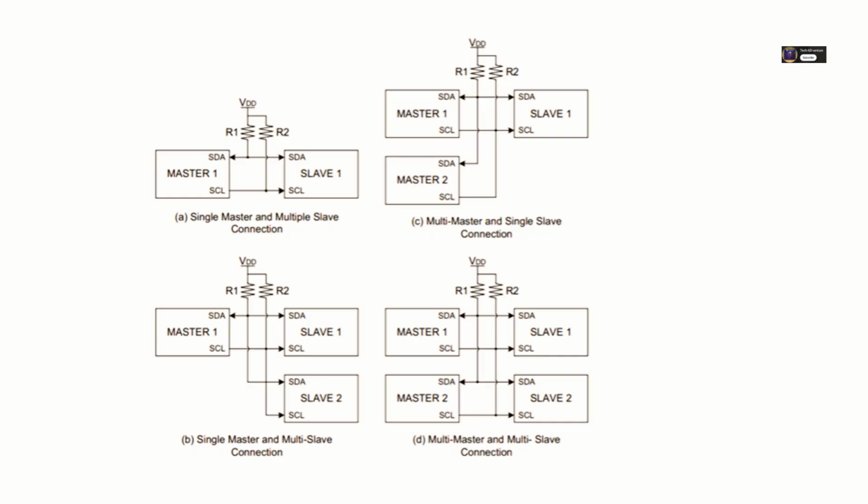And is this also why the single SDA line can handle data going both ways? Bidirectional flow? Exactly that. Because any device can pull low, and any device can let go for the pull-up to take it high, the same physical wire works perfectly for both sending and receiving. One moment, a master is transmitting, pulling low for a 0, letting go for a 1. The next moment, it can switch its internal state to be an input and simply read the voltage level on that same line, determined by a slave that's now transmitting. This inherent flexibility is key to I²C's two-wire simplicity. It's why you get so much function from such minimal hardware.